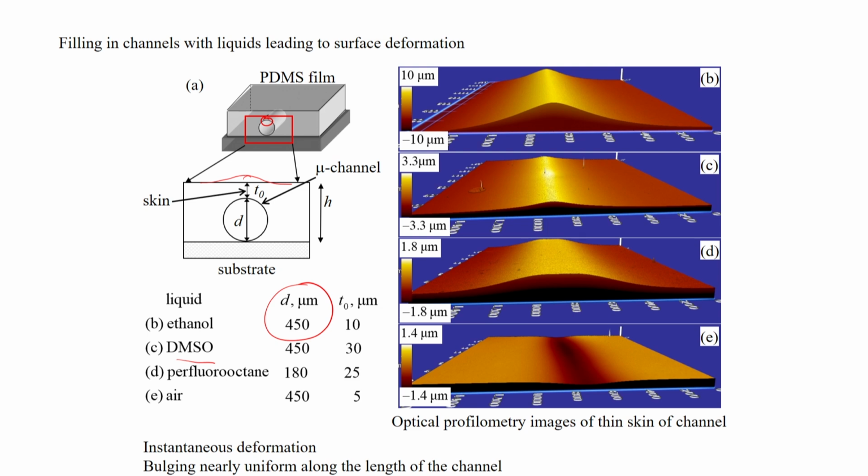So this effect is called elastocapillary, because it is the capillary tension or capillary phenomena that gives rise to this deformation in the elastic film. Basically, it is because of the change in the interfacial tension or surface tension of a solid that leads to this deformation.